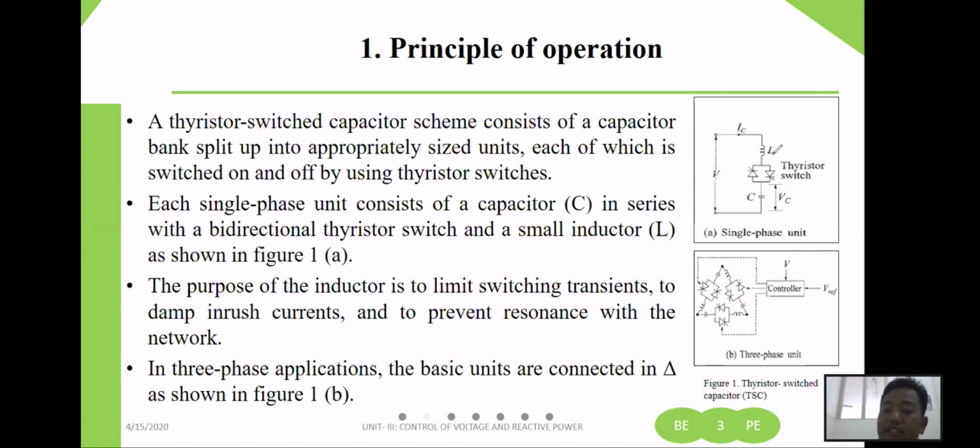To avoid that, choose T1 such that the bus voltage is maximum and the capacitor voltage polarity and bus voltage polarity are the same, to ensure transient free switching.